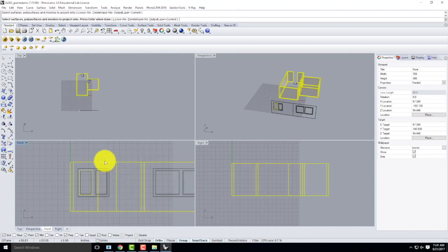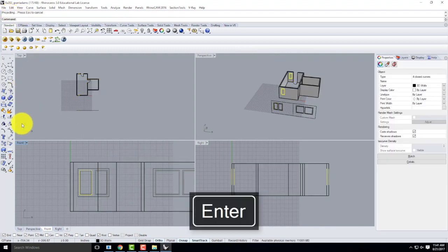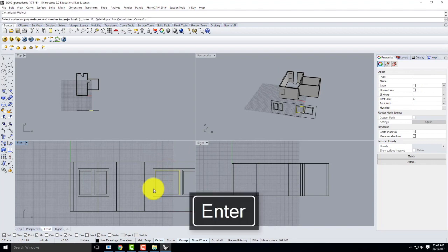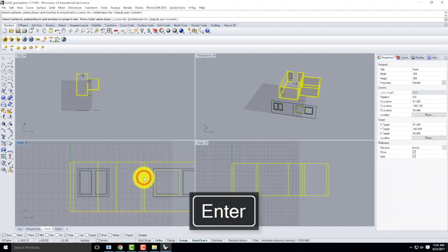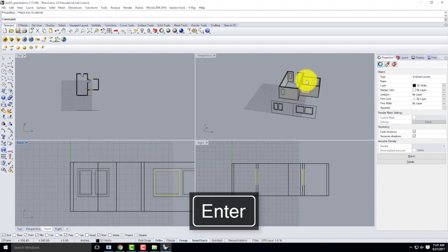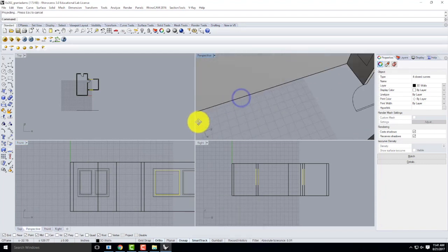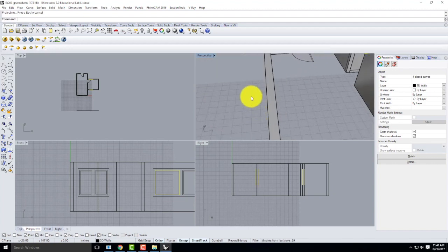I select it. Notice that the selection happened in the front view, not in the side view. And I'll show you how this doesn't work in just a second. So I've gone ahead and I've selected it. I'll go ahead and press enter. And it then takes that rectangle and it throws it out across the 2 surfaces in a straight direction. So I could repeat it using one of these. For example, I could go project onto this surface, and it'll throw those. It puts them on both surfaces of the wall that it goes through. So they're on the front side and they're on the back side.